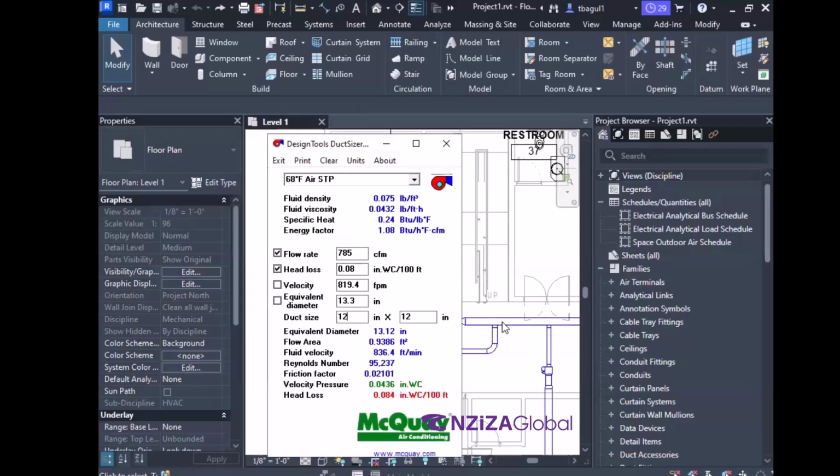Okay. So in a given project, try to minimize the given transitions to the best possible optimization. It's not like we can have just 12 inch by 12 inch throughout the project. Don't do that. Have 2-3 transitions, but make it reasonable so that the design is optimized. This also will come into picture when we are talking about the space. Dual duct systems that we spoke about on day one, space was a big issue, right?